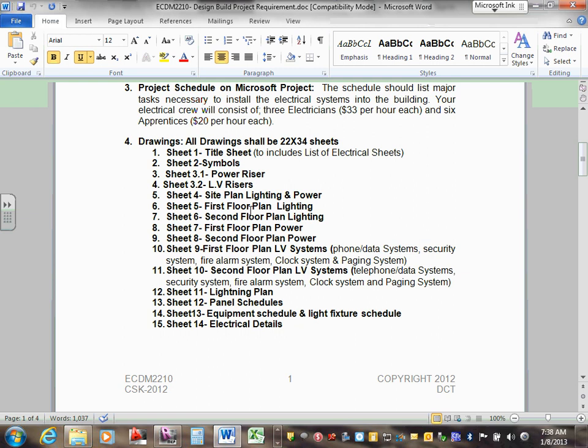So what we're gonna do, guys, first of all, here's the steps, the best way to do it. The title block that we did for the commercial project is already there. We're gonna take the title block, copy it, put it in a location, and name it Industrial Project. Then we're gonna load it into these 14 sheets that we're gonna create. Cool? So you guys should have the title block. We have a title block already created for the commercial project. We're going to copy it. I don't want you to edit it, and we're going to insert it into 14 sheets.